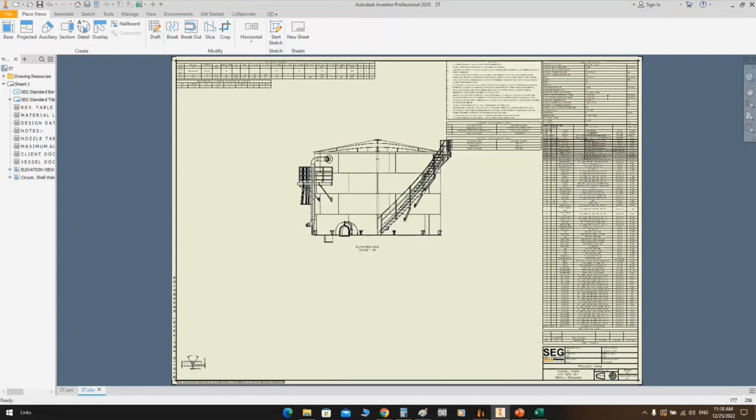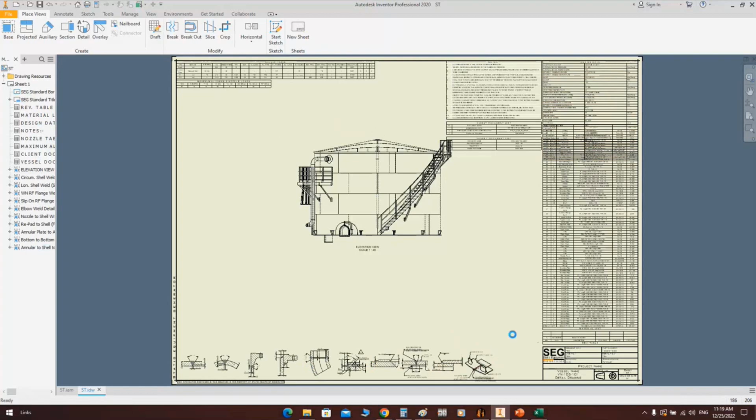In pressure vessels, we need a lot of information for the design code, the maximum allowable working pressure, the seismic and wind code, a lot of things like testing of the material for shell, nozzle, all of that. But here we can make a modification to decrease the number of values in the design data, and we will reflect it again to the drawing. Here you can see that the welding details take place in the drawing. Okay.